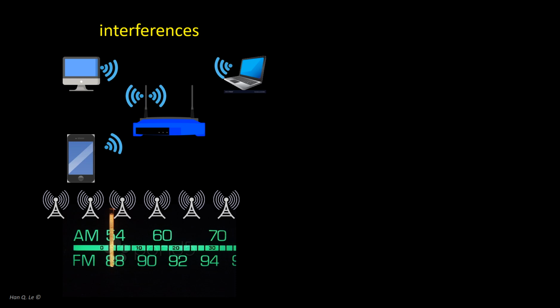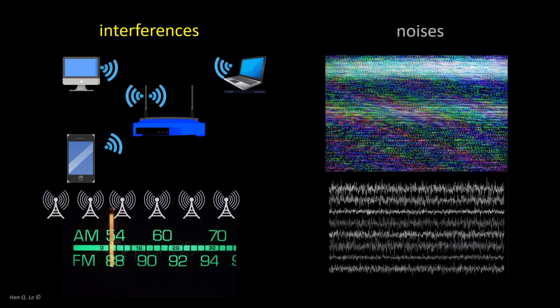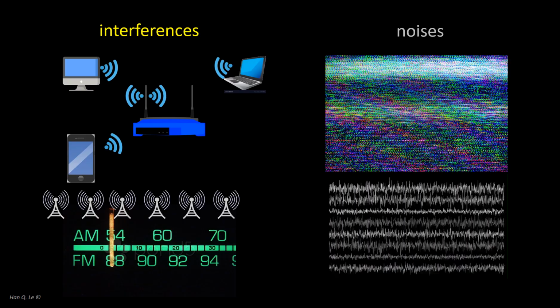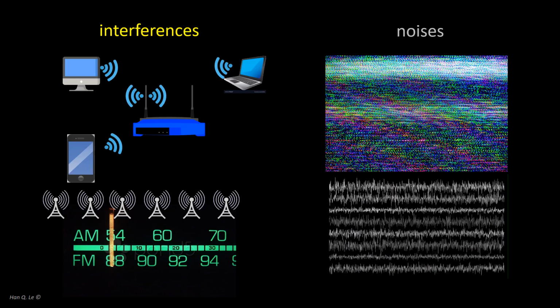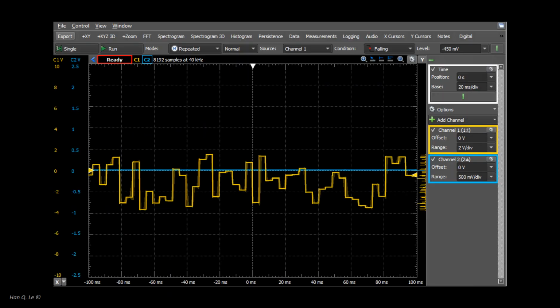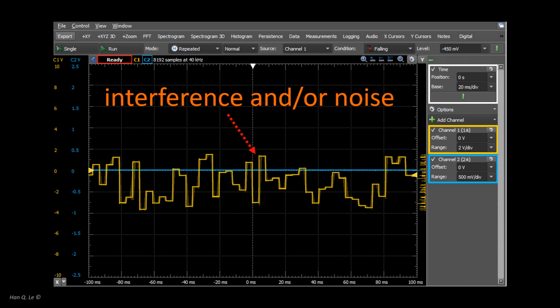Besides interference, there is something else that is always there in any channel of communication. Noises. Noises often show up as static, whenever the communication signals are weaker than the noise power. Hence, communications always involve interferences and noises. For simplicity, in this work, interferences and noises will be simulated with the random amplitude square waves as shown. This is not typical shot noises, thermal Johnson noises, or 1/f noises that are common in electronic communications, but it is sufficient to illustrate the concept for the educational purpose.